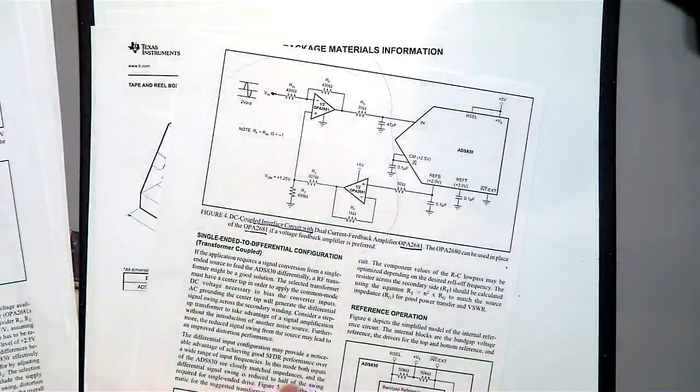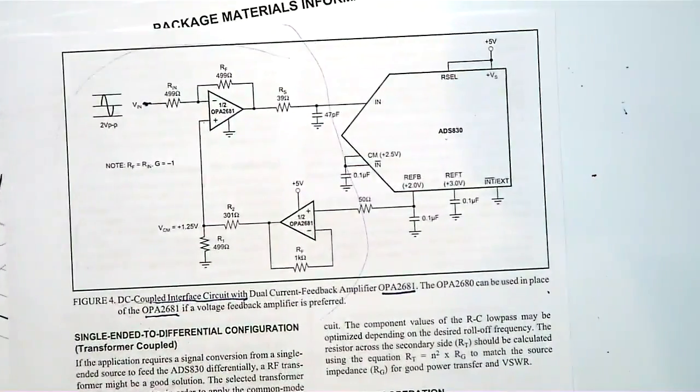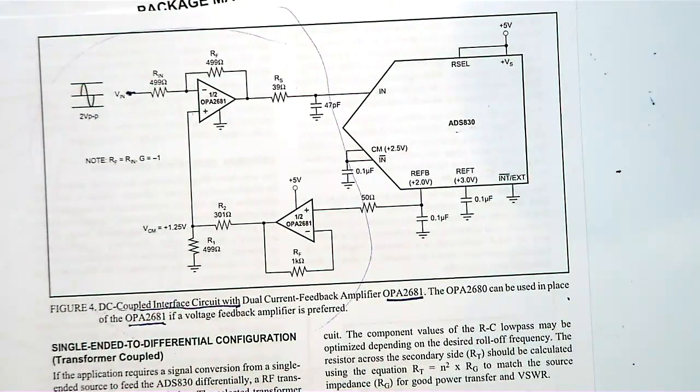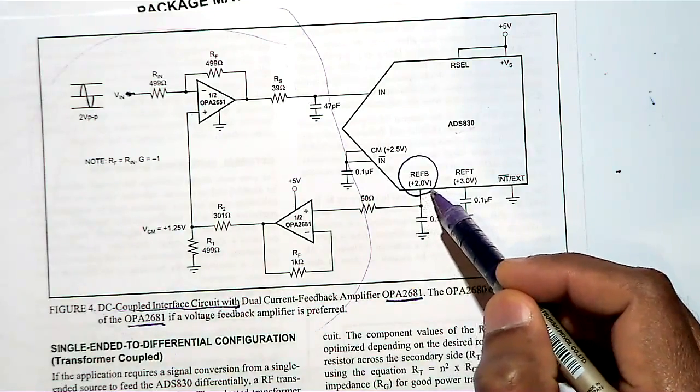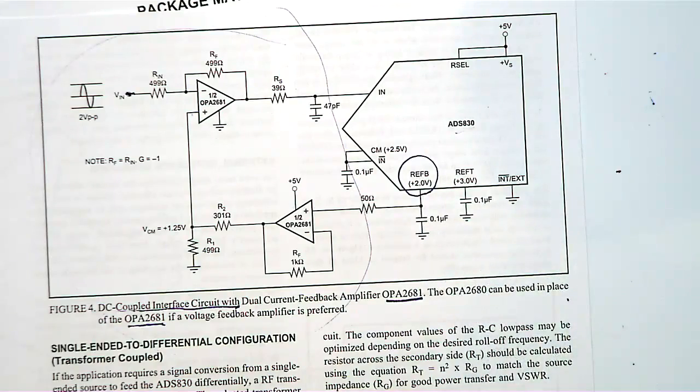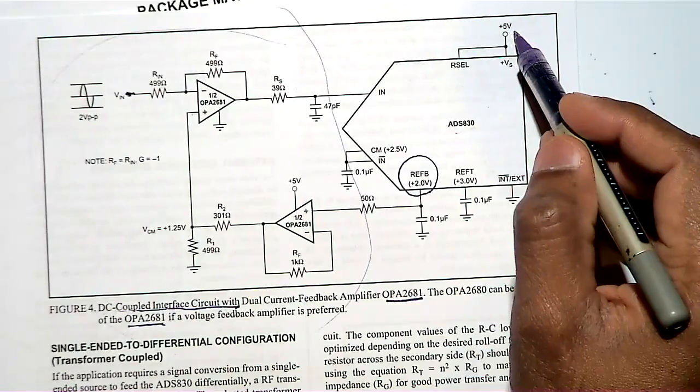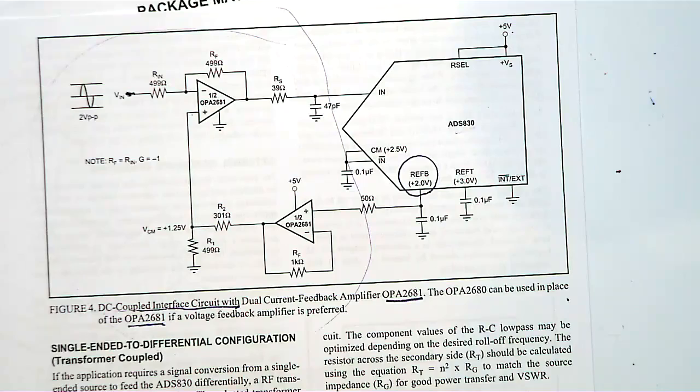So that is the reason here, if you check it, they already said that 1 volt, see how they are generating that volt. So they are getting some voltage from the ADC itself, that is called a reference voltage, 2 volt. So the ADC is giving you a 2 volt reference voltage. So what do you mean by the reference voltage? Whenever you want to generate a reference for the ADC, like level shifting, here you will be connecting a power supply, see plus 5 volt, that is an external power supply. But in the ADC they have some very good circuit, and that will generate a reference voltage that will not fluctuate. Even if your external 5 volt is fluctuating a little bit, the ADC reference voltage will be constant at 2 volt. It means small fluctuations will not affect it. So that reference voltage we can use for generating a level shift.